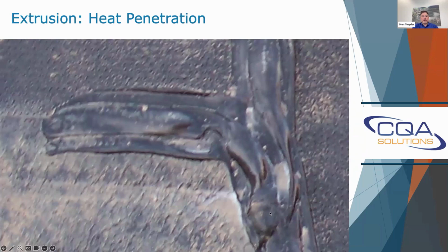They have to come from different directions. They're going one direction to put the weld down, then they come back and either make one pass, or in some cases, they'll make multiple passes to complete the T. So this area in here is being reheated several times, and it's already been heated up by the fusion weld, and they trim the lap off to make these T beads, so you're putting it right on top. So you're already reheating that area, and it's a common area for burn through.